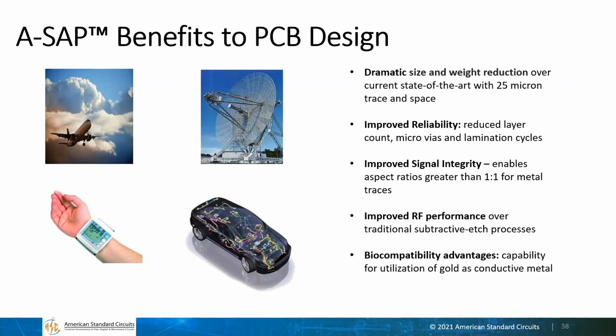So instead of using copper for the trace, we can make the traces out of gold and platinum and palladium, and we can make the dielectrics out of LCP or polyimide. And with no chrome or nickel or anything else needed to connect these metals to the substrates, you have materials which don't cause any allergic or toxic reaction within the body, and in the case of LCP, don't absorb water and can stay happily within tissue for weeks or even months at a time.